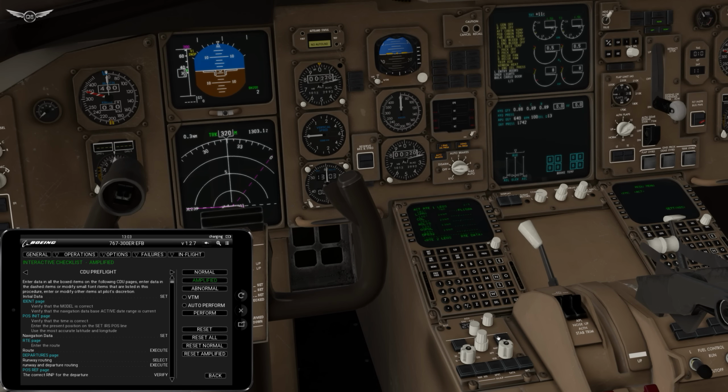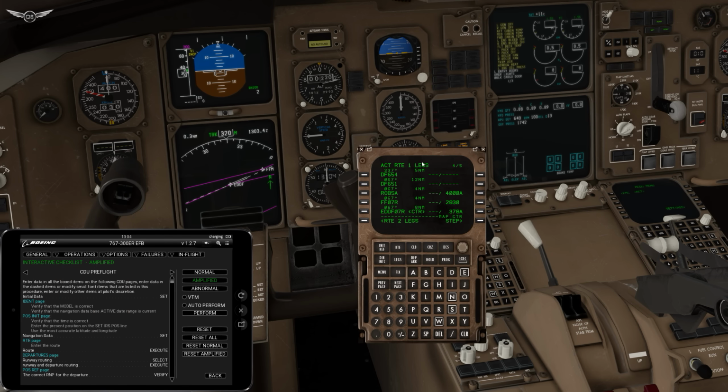So we're going to switch this to plan. And now we can step through. So we're going to step through. That's our departure airport. And that's the SID. And that's Cole. That's Rolls. That's the beginning of our star into Frankfurt. And then we're going to come here and do this nice rectangle shape movement until we intercept the localizer and the ILS to runway 07 right at Frankfurt. So everything's looking good. We're going to now head back to the performance page.